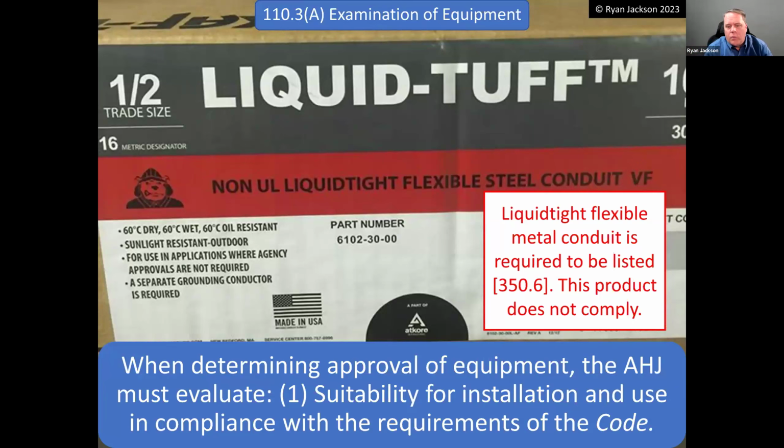Number one, we need to figure out, does this stuff even comply? That's probably the first question that needs to be asked. Suitability for installation and use in compliance with the code. So here I've got this liquid tight flexible metal conduit. Now I mentioned not everything has to be listed, but liquid tight flexible metal conduit does have to be listed.